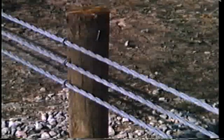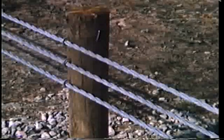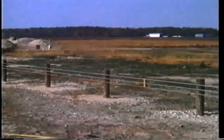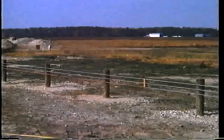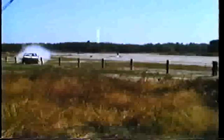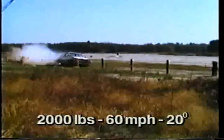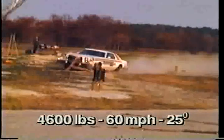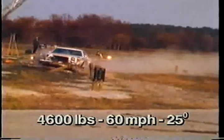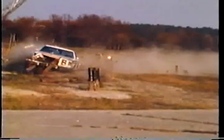This hole helps to weaken the post in the longitudinal direction, ensuring that it breaks away when hit head-on. The post spacing used is 12 feet 6 inches, rather than the 16 feet typical for G1 systems. This small car was successfully redirected without exceeding the allowable occupant response values. The system was also strong enough to contain and redirect this large passenger sedan. The maximum barrier deflections were comparable to the standard G1 system in these two tests.